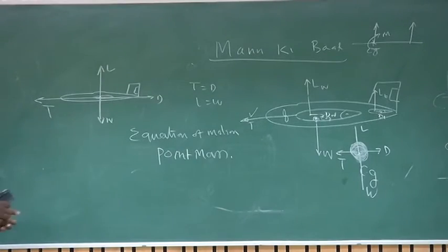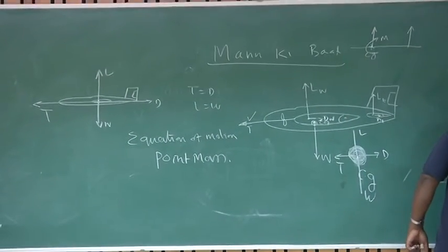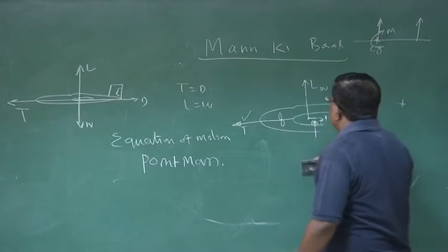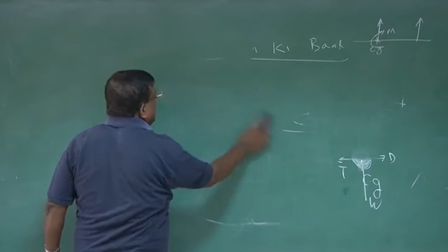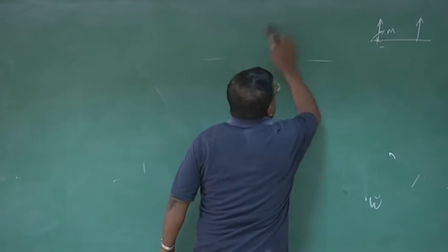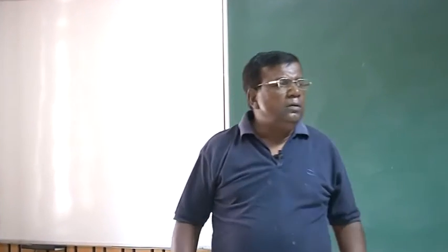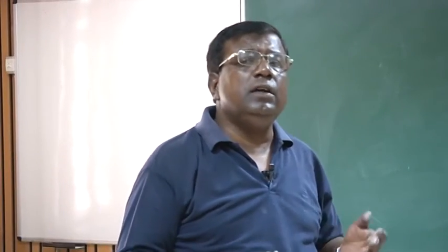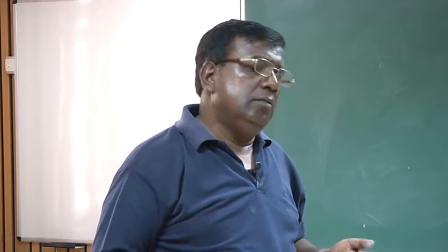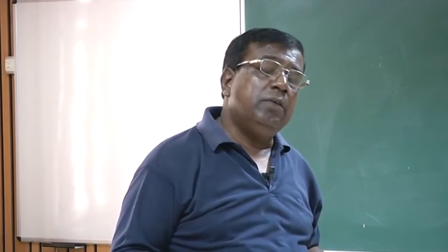Then we were also discussing rate of climb, and we have seen that rate of climb is related to excess power. But one thing I must tell you, for this sort of unpressurized airplane, aerodynamically their ceiling or service ceiling altitude will be much higher than actually you can fly this machine for other conditions.